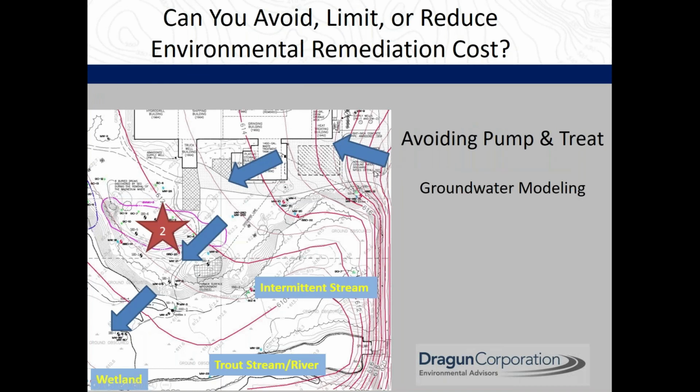But looking at the groundwater contouring and monitoring well data, we were able to confidently show that the plant area was not a significant source, and that the main source of groundwater contamination was coming again through infiltration through the fill areas. And through that groundwater contouring, also able to show again where it's coming onto the site in that upper blue line area. Those water wells are just above that arrow, that there's clean water coming to those wells.